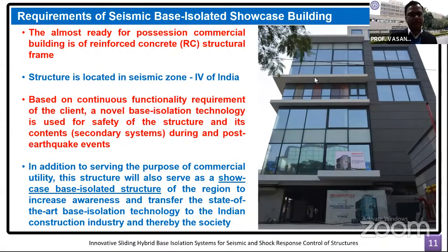And the requirement, as I have said, is continuous functionality and to introduce the novel double curvature friction isolation system to protect not only the main structure, but also the contents within it. And the motive behind this structure was also to showcase the base isolation technology and to transfer some of the state-of-the-art research in base isolation to the Indian construction industry.